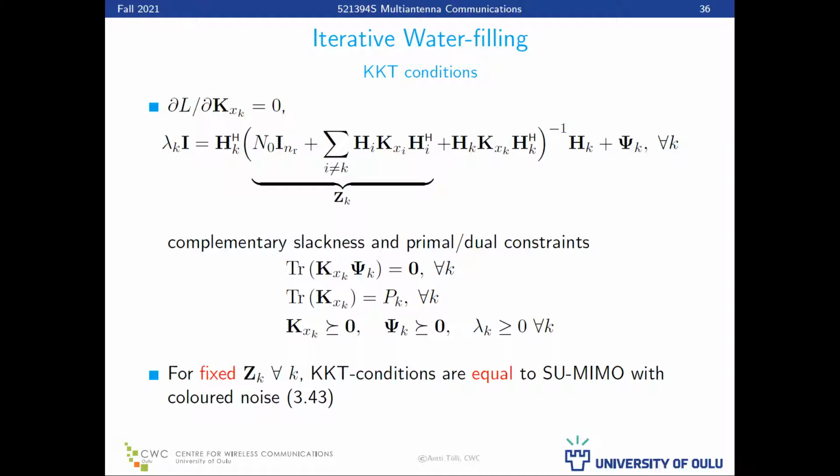Okay, so it's easy to show. The more details you can find in the paper. But when you start doing the block coordinate ascent update of this, basically start from somewhere and assume all other transmit covariance matrices as fixed, at each step you're guaranteed to increase the objective, right? So this suggests this practical solution, what we call iterative water filling.